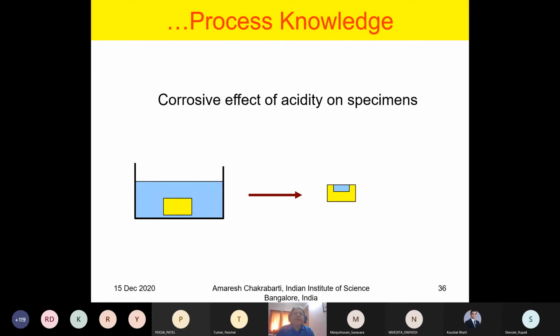And that therefore is not a great solution. However, you can think of this solution also, where you make a little hole on top of the specimen, and then you put a drop of acid there, you leave it for a while and take it out. And now you are using the specimen as an acid bath, right? And that solution is much cheaper because you just need to modify the shape of the specimen, and you need far less acid also, and you don't leave this expensive lining.